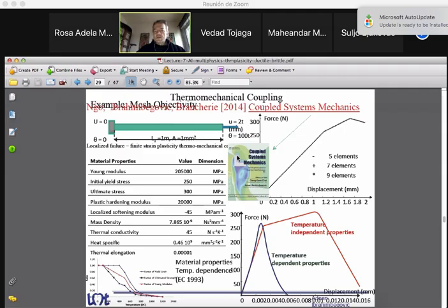So what is the consequence of this choice? You can see here, if you have temperature independent properties, you can push this steel bar into very large deformation. And you recall, whatever is the dissipation, it's the area underneath this curve. Then you bring it to the first yield, then you bring it to the ultimate saturation stress, and then you go down to something. So without temperature dependence, there is a sizable contribution of the plastic dissipation. With the temperature dependence, you go down.